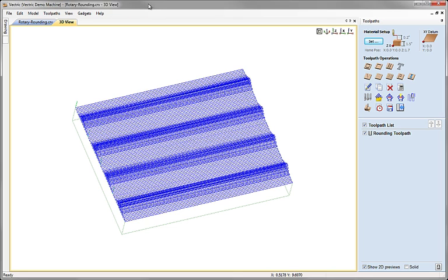The other options we looked at in the example under the gadgets and wrapping were how to use this to help you lay out the vectors for doing fluting around a cylinder, how to use this to help you lay out the vectors to do spirals around a cylinder for something like a barley twist, say, with a round over bit, or, as we looked at the end there, how to create a special type of toolpath that'll help you to create that cylindrical stock in the first place. That concludes this tutorial.